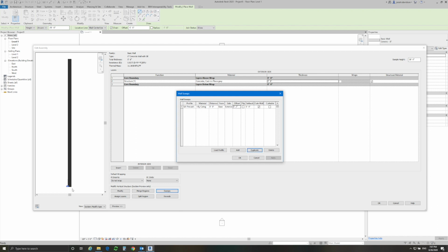Now you can see that the profile is now at the base of my wall and is 2 inches out of the exterior side of my wall. If I wanted to increase that to 4 inches, I could just enter 4, and of course, just like with the distance column, I can enter a negative number, like -2. Now you can see the sill sits right outside my wall, which is what I'm looking for. If I wanted to flip this profile horizontally, I could click this flip checkbox.